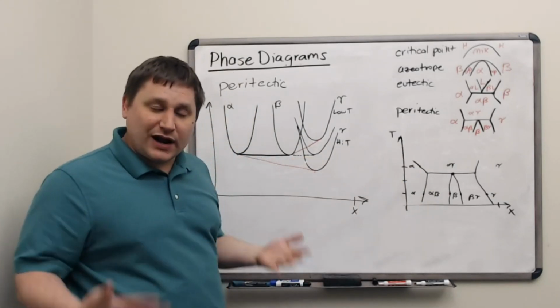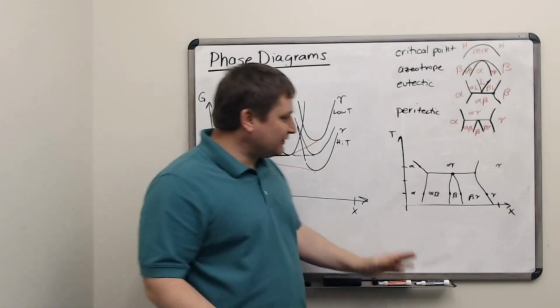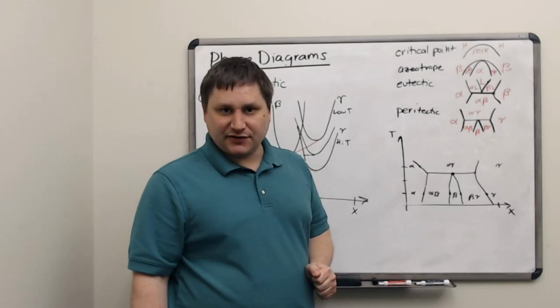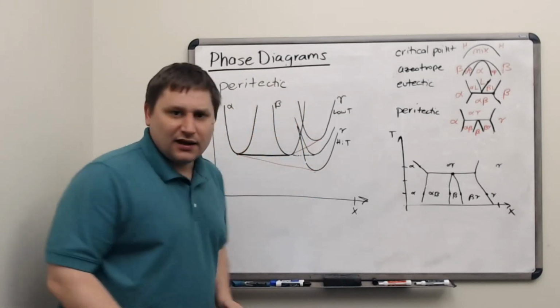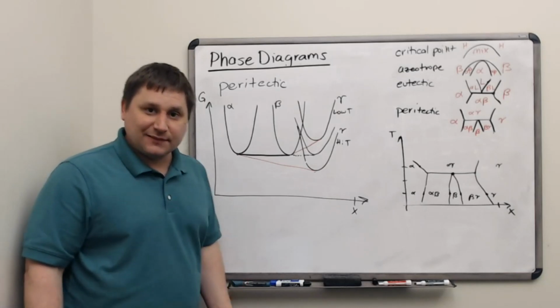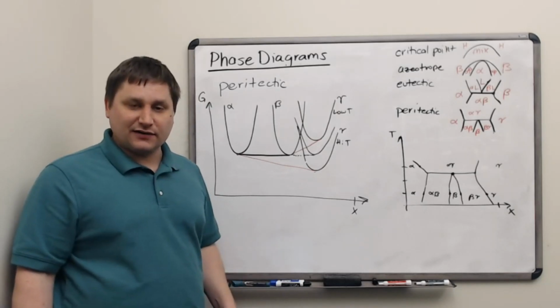But whenever you're in one of these mixture regions, you can use the lever rule between 2 points on the edges at the same temperature. Okay, let's look at some phase diagrams for realistic systems and see if we can identify this equation, this behavior.